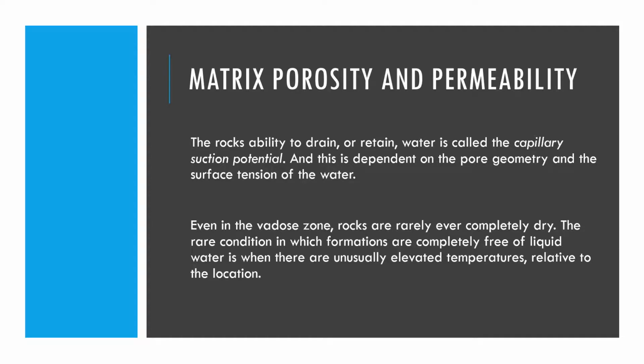So this is a concept that you can kind of think about and you'll get it, because since there is a water table below the vadose zone, and since there is a saturation level below that, at least the rainwater will have to go through that vadose zone and seep into the water saturation level, if it ever reaches there, honestly, because depending on the rocks or the material that exist and their capillary suction potential, we don't know how dry or unsaturated the vadose zone can be.